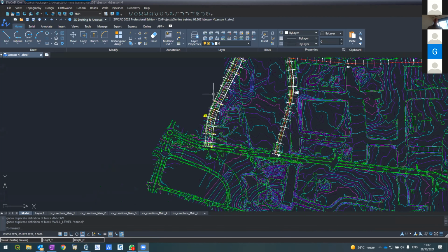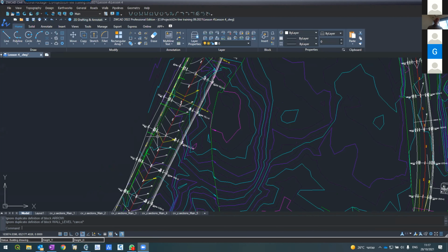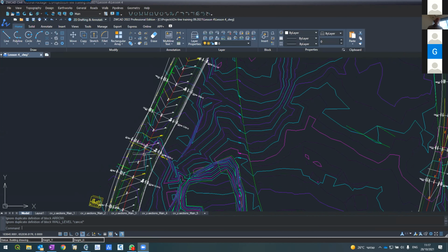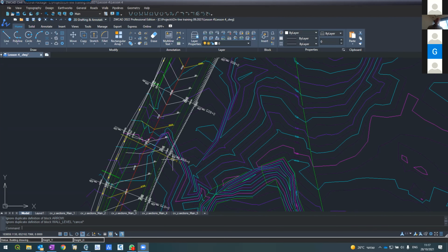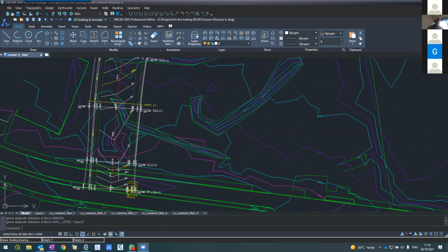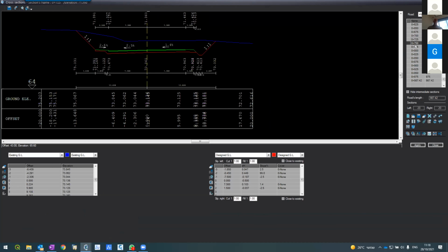Here it is. This is the first transition, super elevation, going here. Here the straight line, the tangent is up straight, minus 2.5. And here, this is the tangent. 20 meters before the tangent, I started super elevating until 10 meters after the tangent. And going back here. Questions? Quite complicated, but worthwhile. Any questions?